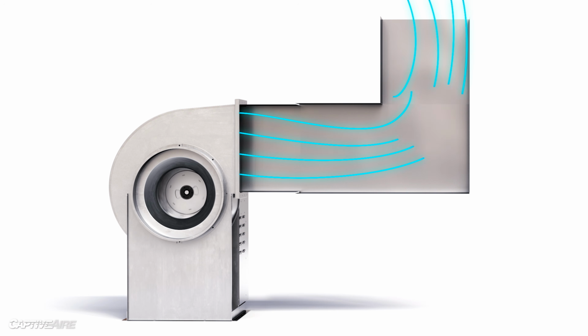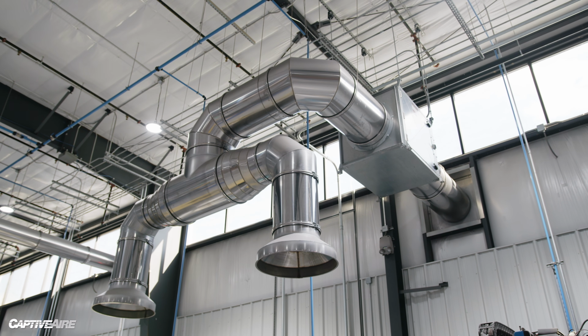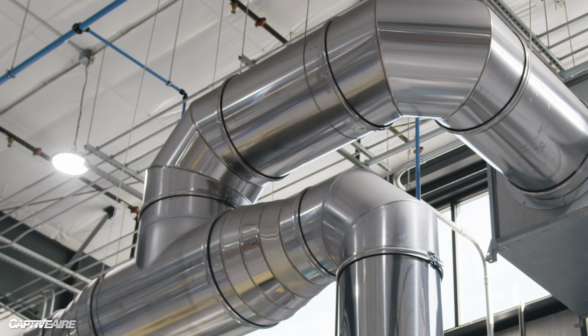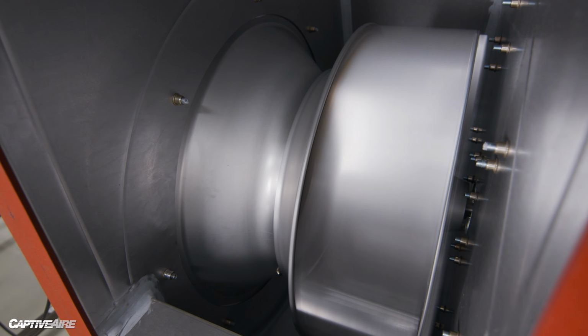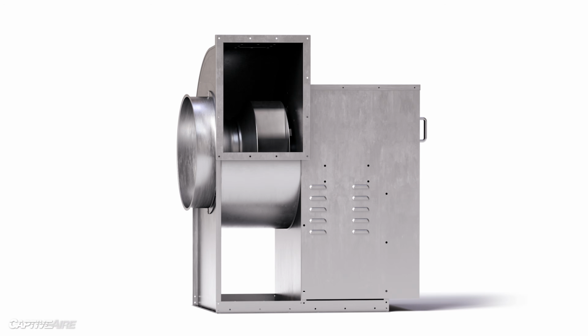For example, if you put a 90-degree elbow right near the inlet or discharge of the fan, that's a form of system effect. Or if you put turns in a duct very close to one another, where one turn or elbow can affect the second elbow, that's another version of system effect for the duct itself, not only the fan. So you have to be aware of all these system effects and dynamic effects in the field to accurately size fans for the application.